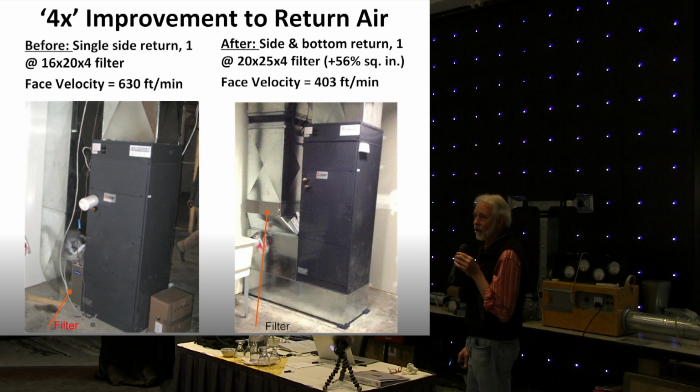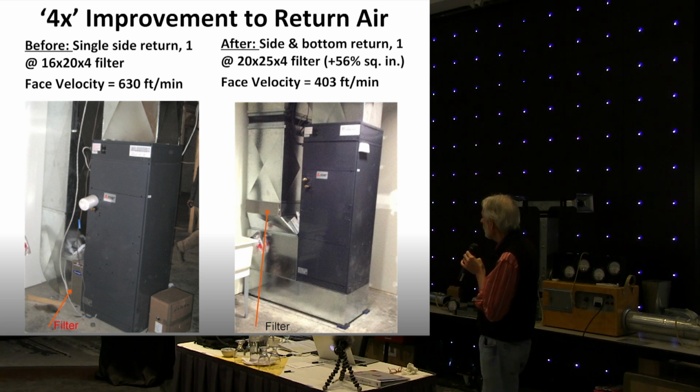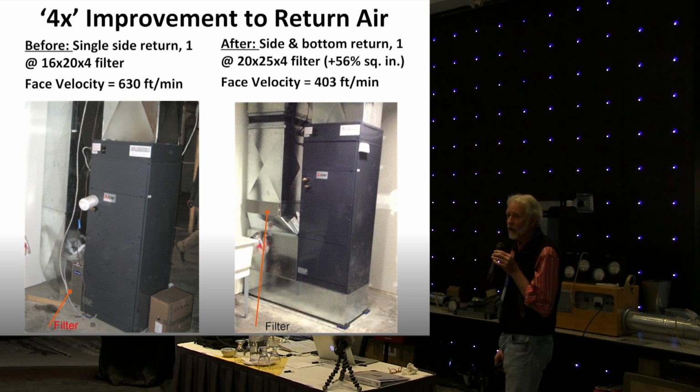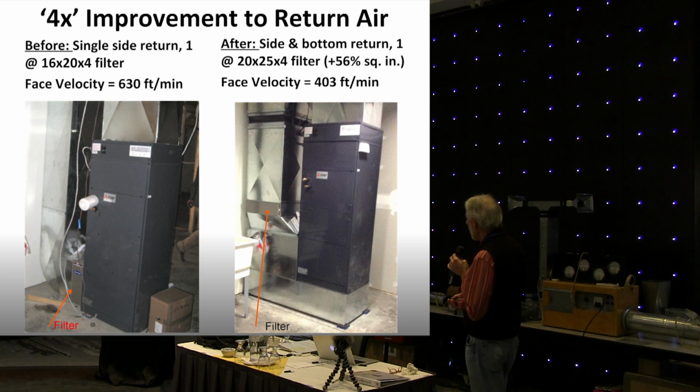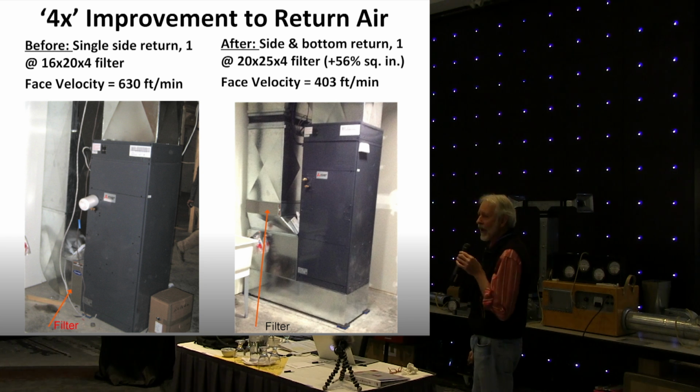Next time I went to visit there, I found out later by the back channels that there was between $1,000 and $2,000 worth of duct changes. And finally, surprisingly enough, the equipment had been reinstalled on a bottom return, and was actually installed to meet the manufacturer's minimum requirements that were in the installation manual that were in front of the contractor all along.